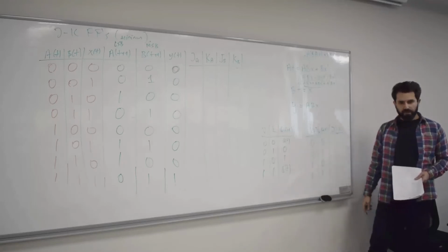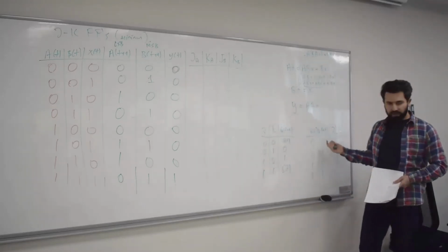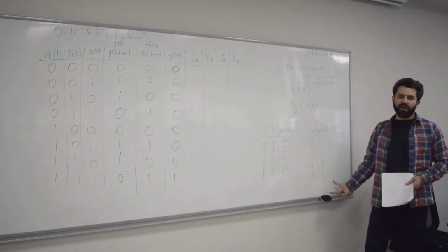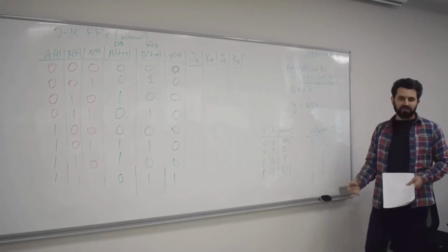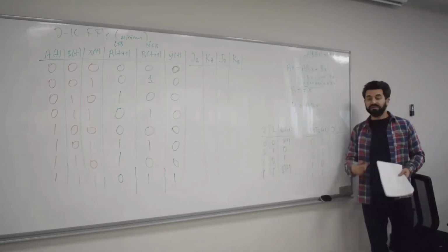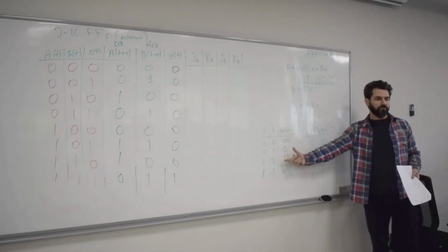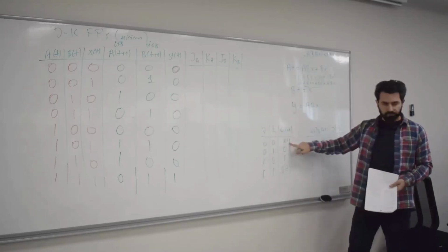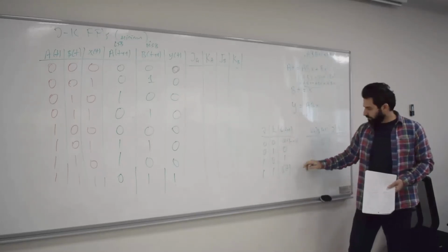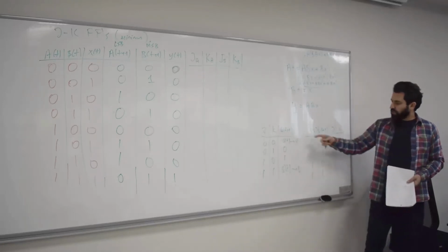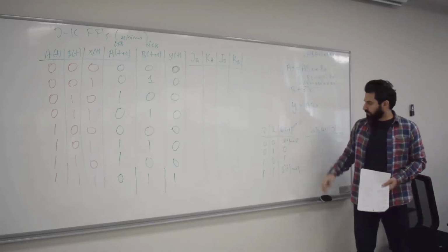Okay? So, it's kind of easy to derive this table, but you don't need to derive it or memorize it. You can actually use your cheat sheet to copy-paste your excitation table, so you don't need to memorize. But I just want to show you how this excitation table is derived from the characteristic table. Okay? So, by just looking at this, you see if QT is 0, this is 0, right? This is 1, okay? And QT plus 1 is 0, so this is also 0, okay?